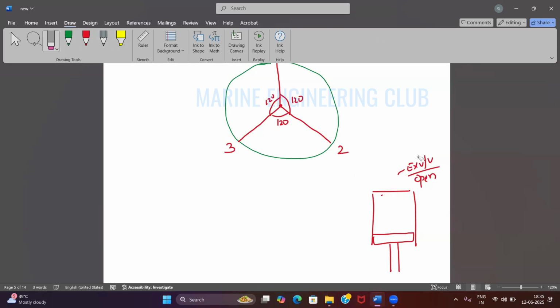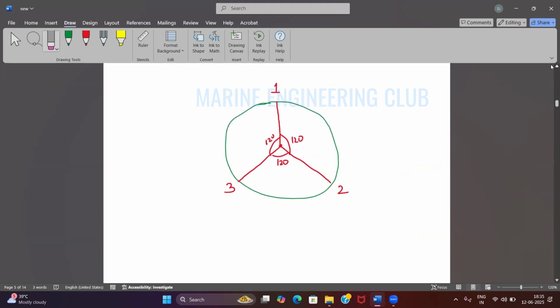So normally, now if I have taken 3 units and I use the starting air manifold, I will use this here to explain why I need at least 4 units to start the engine from any given state. Normally we consider, suppose we start from 0 degree. Suppose this is 0 degree, and my number one unit air starting valve opens here.